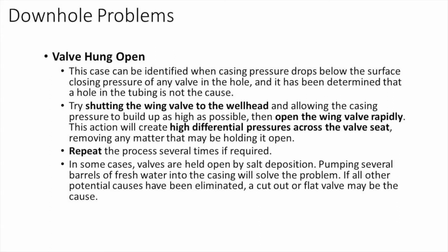So, a valve hung open. A valve hung open can be tied to circulating dry gas. It can be tied to a drop in total gas or total fluid production. And this one's typically caused by debris. Again, we see this one most commonly in new construction, highly active areas where there's a lot of pipelines being put in, and a lot of roustabout work around the well site. So the biggest culprits are welding slag, metal shavings, those types of things that cause the valves to hang open.